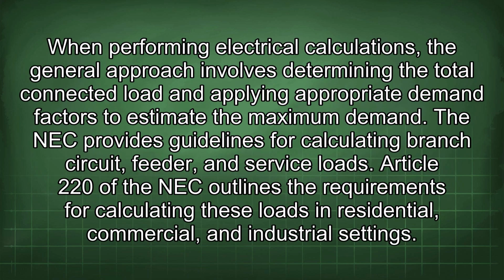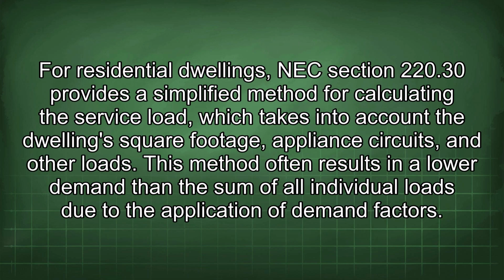When performing electrical calculations, the general approach involves determining the total connected load and applying appropriate demand factors to estimate the maximum demand. The NEC provides guidelines for calculating branch circuit, feeder, and service loads. Article 220 of the NEC outlines the requirements for calculating these loads in residential, commercial, and industrial settings. For residential dwellings, NEC Section 220.30 provides a simplified method for calculating the service load, which takes into account the dwelling square footage, appliance circuits, and other loads.